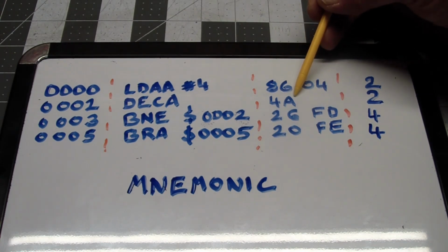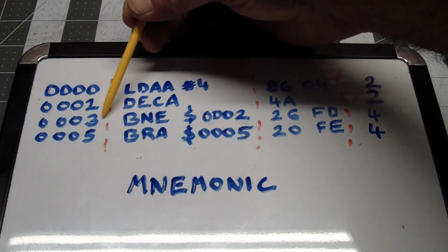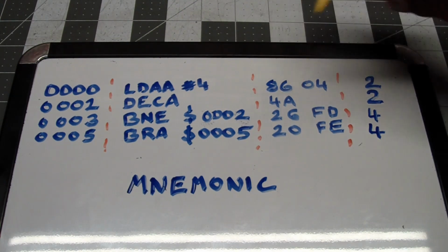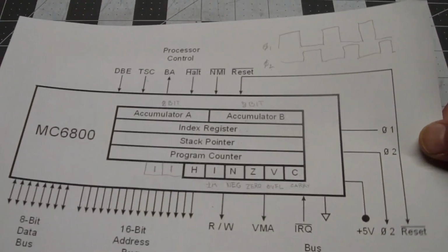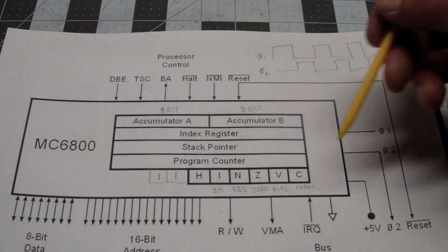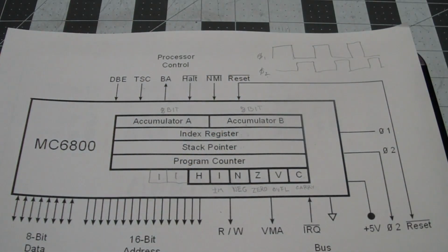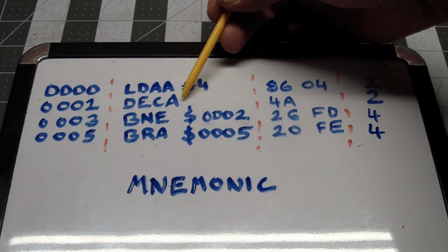It's a single opcode, takes 2 machine cycles, and will advance the program counter to 3 because it only has a single byte over here. Now at this point, we briefly talked about the condition code register. The result of doing an operation on the accumulator doesn't just change the value of the accumulator, but there are flags here that tell us what happened. And as we will see later on, what is very important to us is we jump to the next instruction